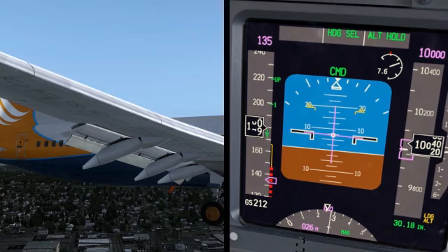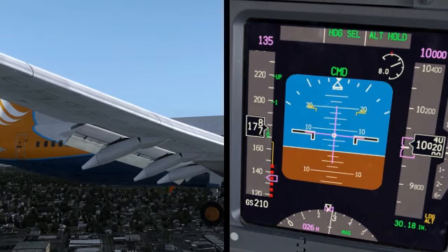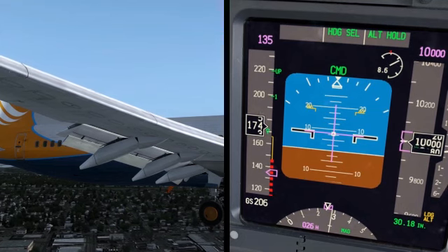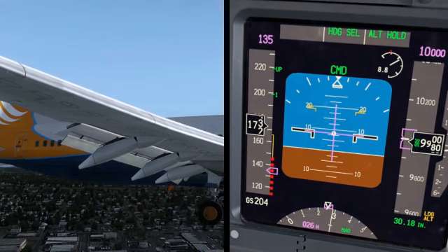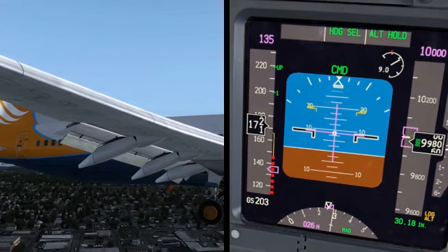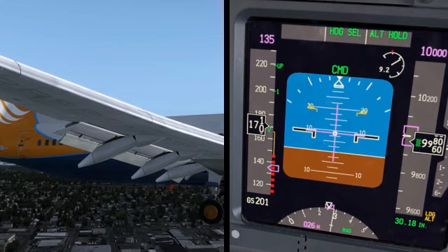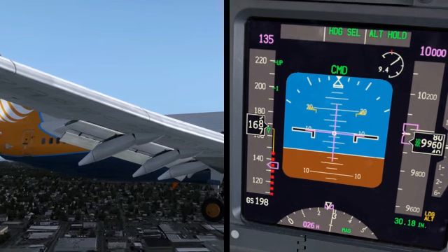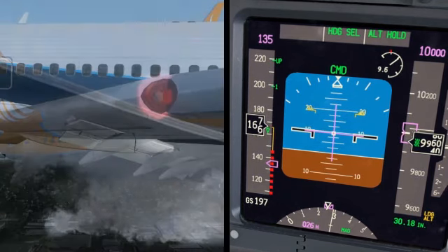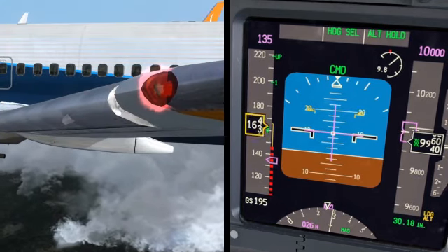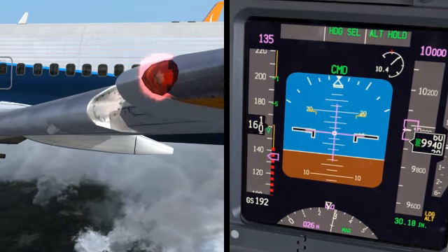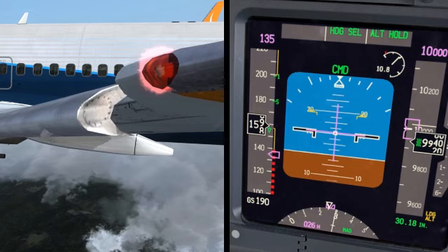Leading edge auto slat function. The auto slat function moves leading edge flaps to the fully extended position when the system senses that the aircraft is approaching a stall condition. Autoslat operation is powered by the hydraulic system B, but an alternate source of power is also provided through the Hydraulic Power Transfer Unit, or PTU. This feature is comprehensively described in the hydraulics lesson.